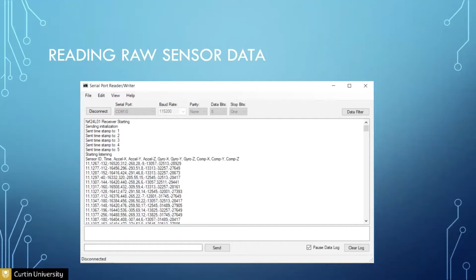If you want to use infrared, you can use RF transmitter and receiver. With sensor. Yes. And the receiver, Arduino with the PC, right? Yes. And Bluetooth. No. If you wanted to use Bluetooth, you don't need to use an RF at all. You can just use two Bluetooth modules, one to send information from your sensor, one to receive the information from the sensor to the Arduino. So I need two Bluetooth and two Arduino controller, right?